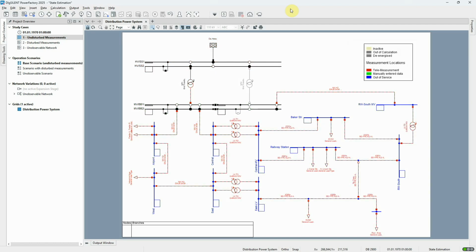The state estimation function is used to obtain consistent load flow results based on measurements that have been imported into PowerFactory, such as branch flows and bus bar voltages. The states to be estimated might include the active and reactive power of loads and generators and the tap positions of transformers. At the core of the function is an optimization process, whose objective is to minimize the difference between the calculated load flow results and the measurement values through adjustment of the relevant element attributes.